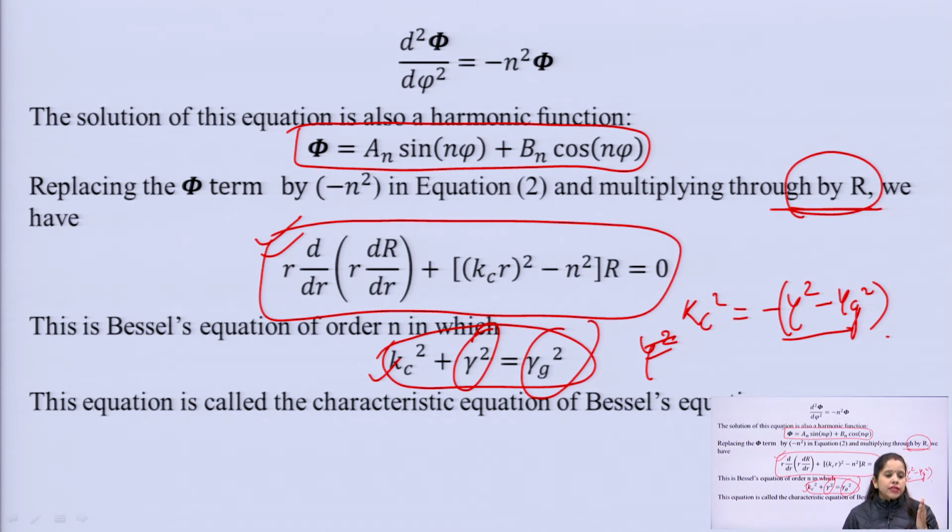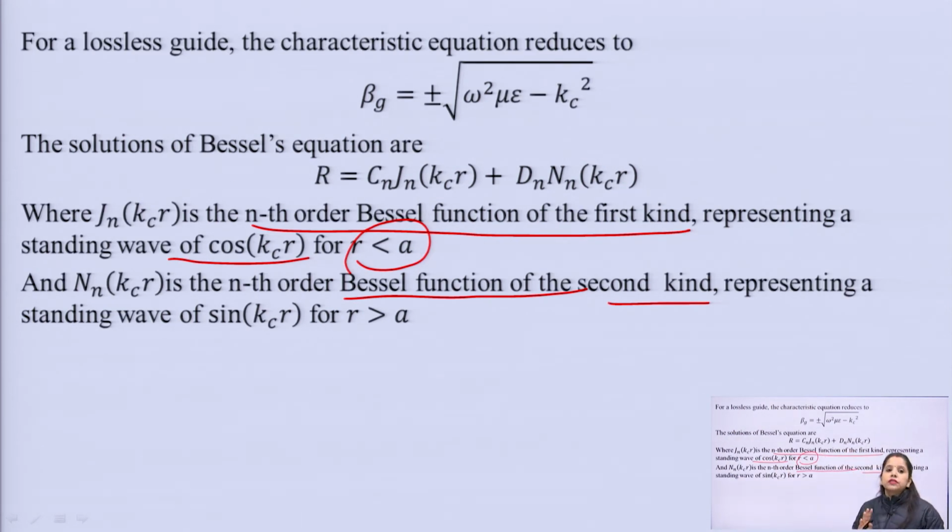First, on the Z function, we are assuming that the wave is propagating in the z direction inside a waveguide. So, we solve that term with the help of the propagation constant of a waveguide, which is gamma g. Next, phi is a harmonic function, so we obtain this, and now our approach is to find R. For that, whatever expression we get after substituting gamma g and phi, we multiply throughout by r square, and gamma square minus gamma g square should be equal to kc square. We will get the characteristic equation, and this equation is in the form of a Bessel function.